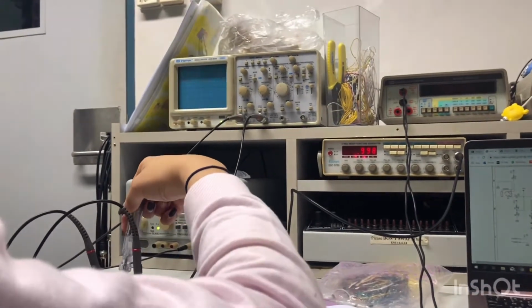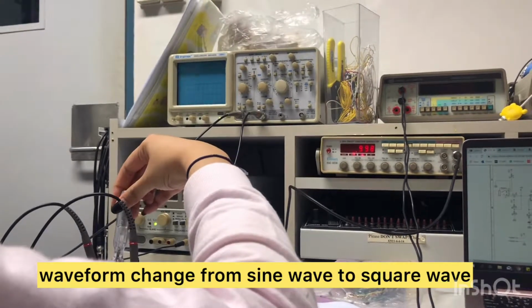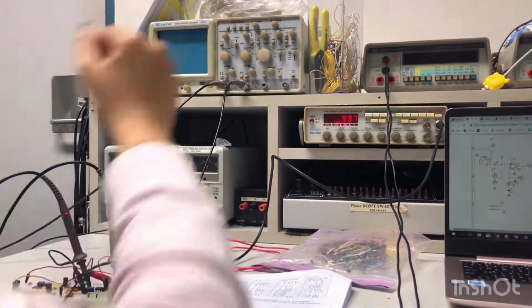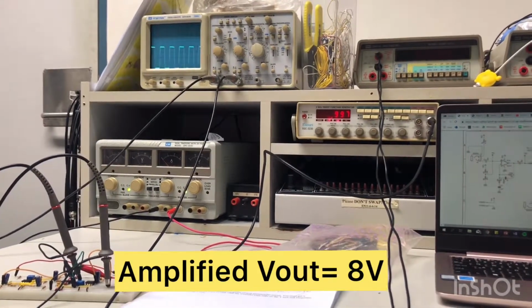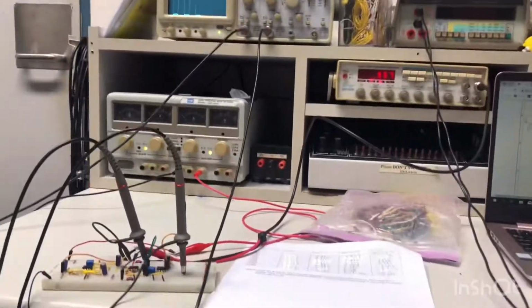So now I'm turning the potentiometer. As you can see, the voltage is amplified and the waveform changed from a sine wave to a square wave. Now the V out has become 8 volts after amplifying, and this shows that my amplifier is working.